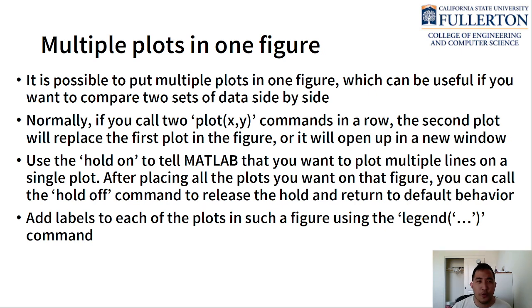It depends on if you call the figure or not. But you can tell MATLAB to actually put these on the same figure using this hold on command. What that tells MATLAB is, hold on, we want to put more data onto this figure, and then it's going to go ahead and do that. And then when you're done, you can add the hold off.